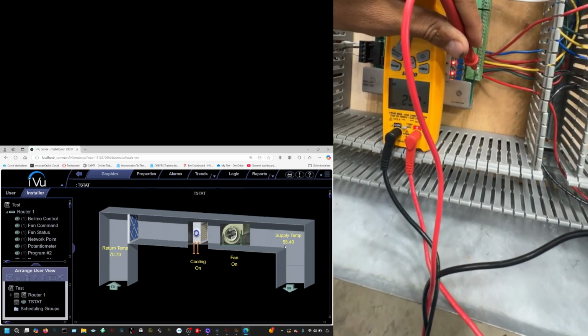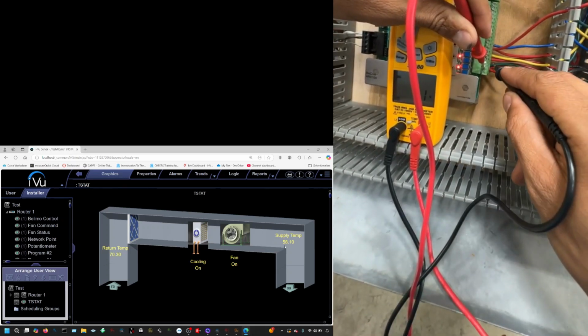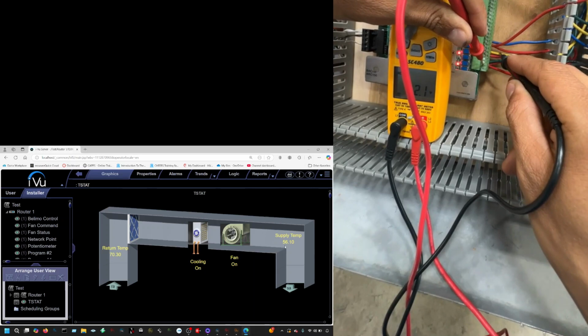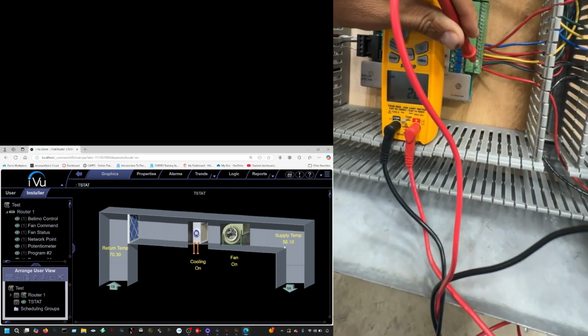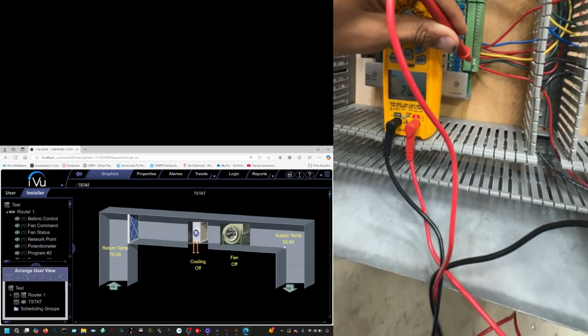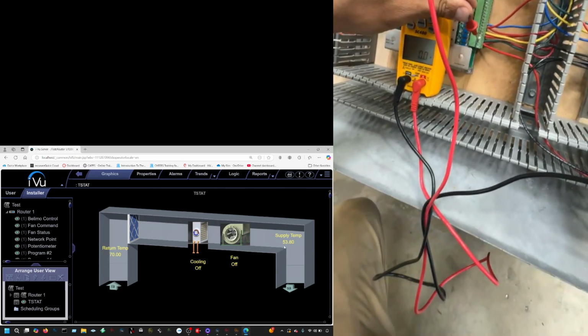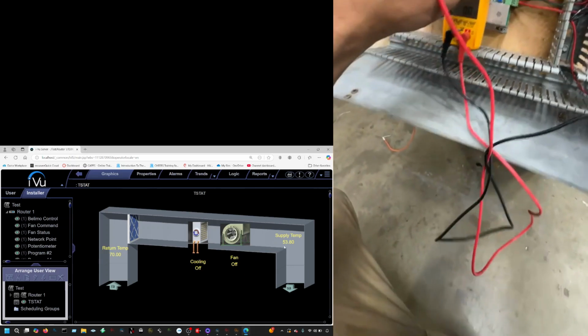My binary output 1 is my contact, my compressor is coming out of this green wire, number 3, and then the reversing valve is the yellow one. I can go ahead and confirm. And you see what happened right now? Now I'm not calling for it. And you know why I'm not calling for it, right? And this is good for you guys to see.